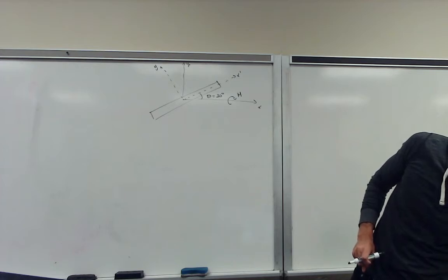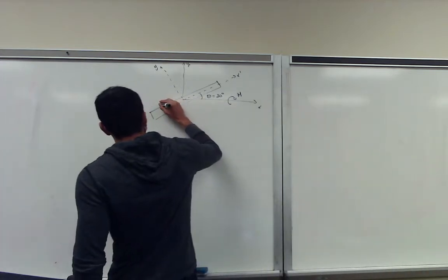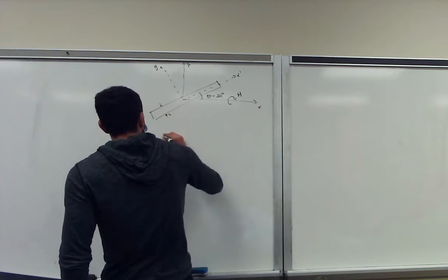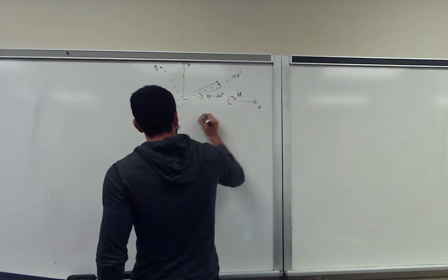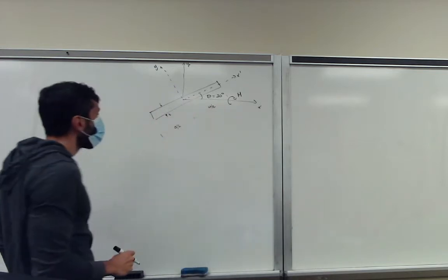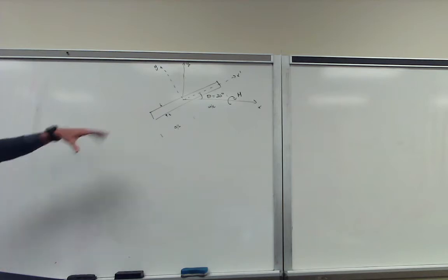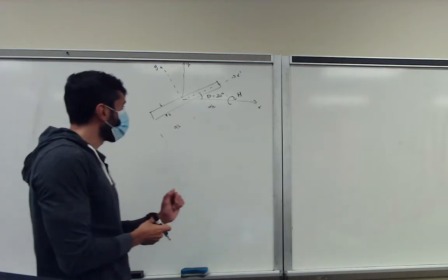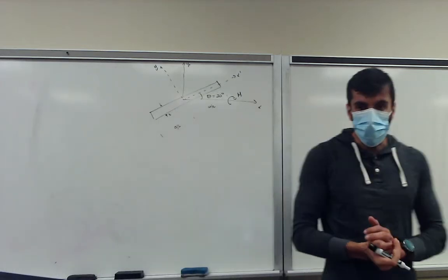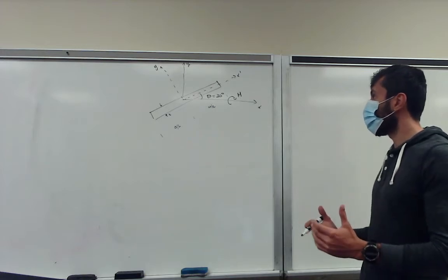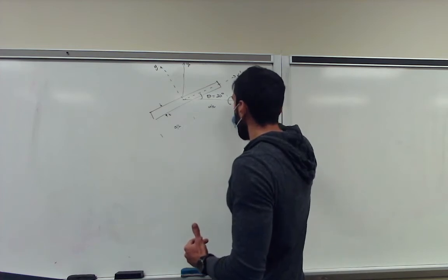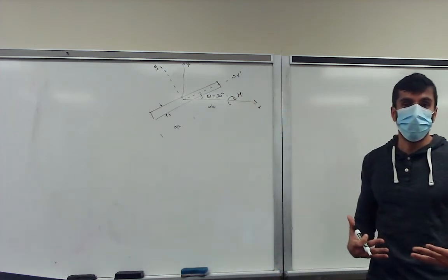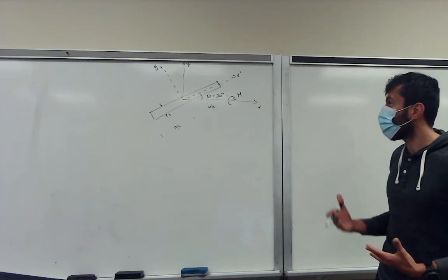Let's see. This is the thickness. And the total length is A/2, so the total length is A. So you have to basically calculate where the direct stresses are, and where the maximum occurs and where the minimum occurs. In this case, we have a beam that's no longer acting on the same axis system as our moment. So we have to determine what the moment is and how it will act on our structure.